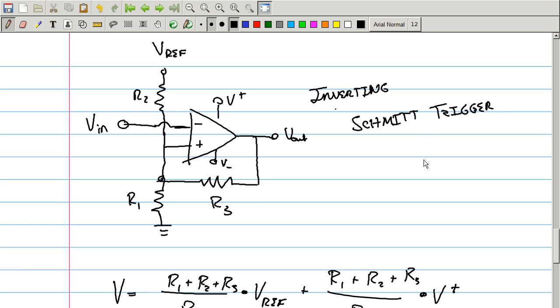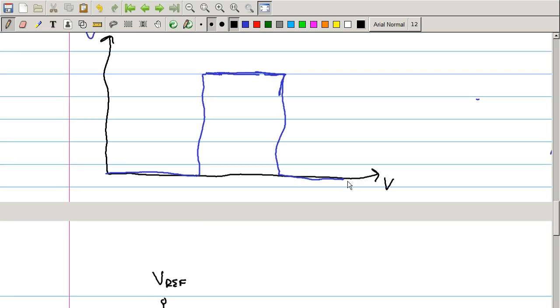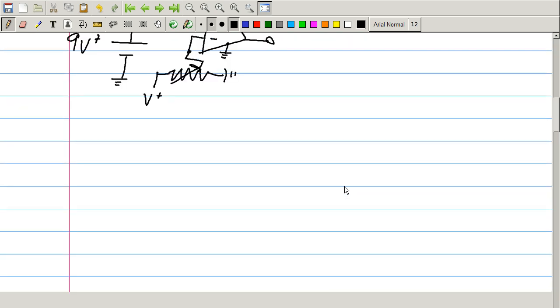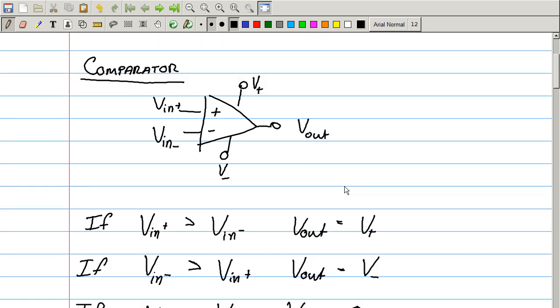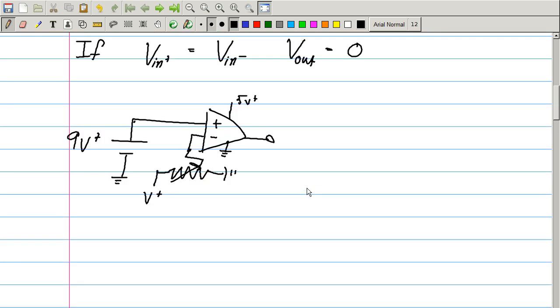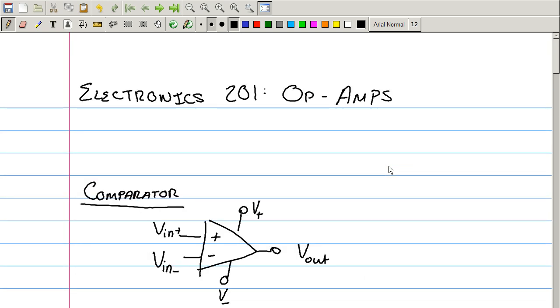So again, Schmitt trigger is good at removing that jitter from an input signal. So it's good at debouncing, say, a digital signal or even an analog signal, as we saw with Falstad. And you've got the comparator. Simpler than a Schmitt trigger, but good if you only want to compare against one voltage. So again, like a battery comparator or a current detector will output a voltage that you can use to compare something to. So yeah, that's the digital applications of an op-amp.